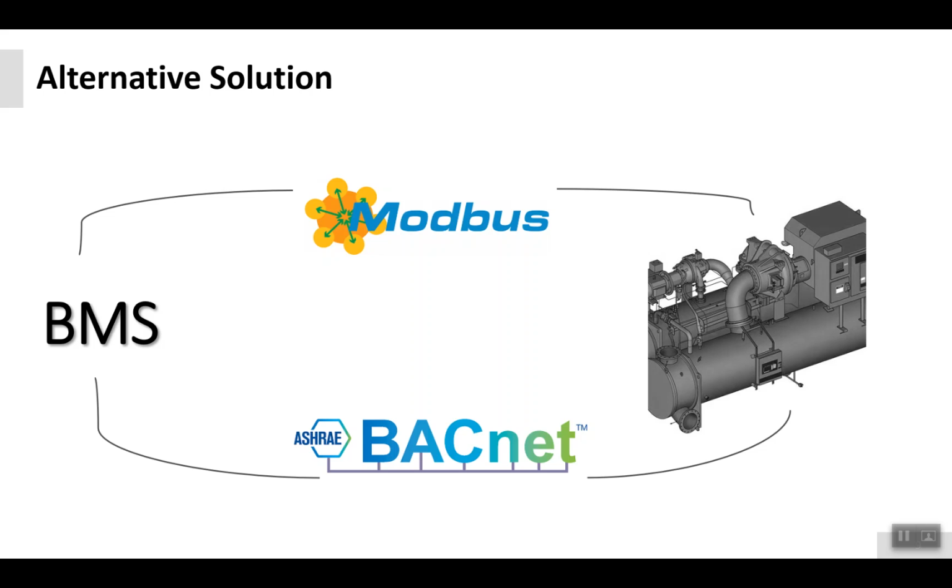Sometimes when you as a BMS person go to the site or study the documents of the projects, you can see the chiller provides Modbus communication or BACnet communication. It makes our life very easy in this case, because most of the time there is no need to install a separate controller or sensors.